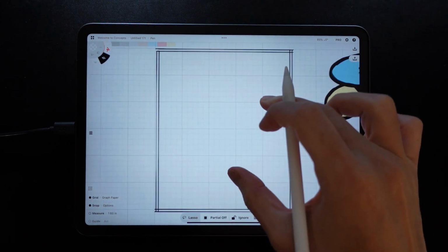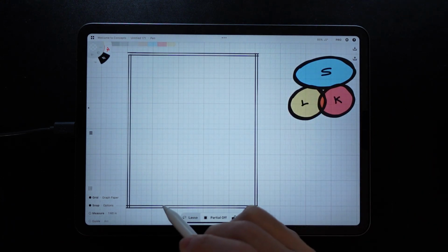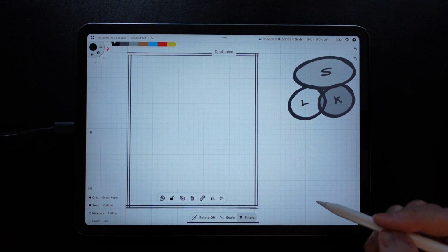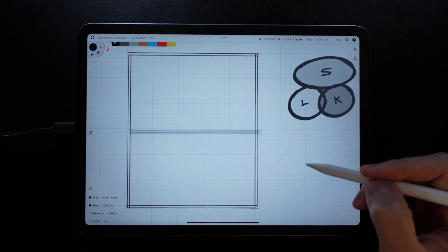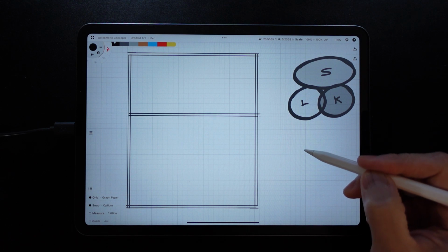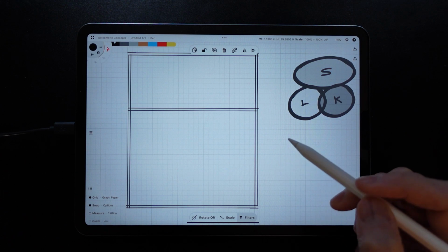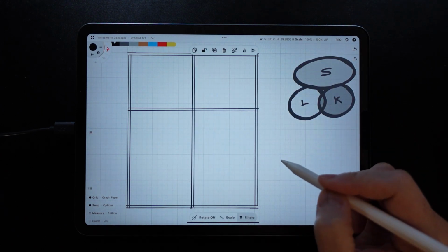So we're just gonna select these walls here, make a copy, and move it here to separate the two spaces. So probably this is 19 feet, which is fine. I'm just gonna grab this one, copy and put it right here in the middle.